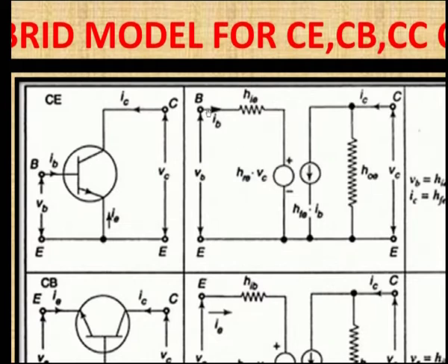So, the input side of the transistor is equivalently given as a Thevenin equivalent circuit, and the output part of the transistor is given as a Norton equivalent circuit. We know that for the Thevenin equivalent circuit, the source is in series with the resistance, and in the Norton circuit the current source is parallel with the resistance. So, that is the concept.